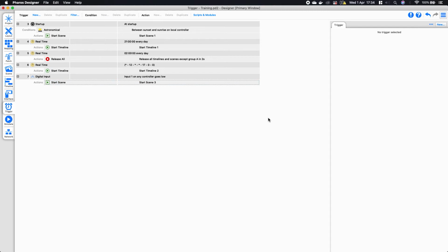So this is quite useful if you want to have a really simple integration with either something like a building management system or a fire alarm, or alternatively, if you just wanted to create something that responds to a normal switch, you can do that as well just by hooking that up to the LPC. I should state there are 2 modes for this. There is the contact closure mode that you can set it to, and there's also the digital mode.